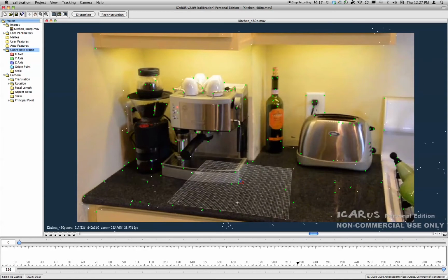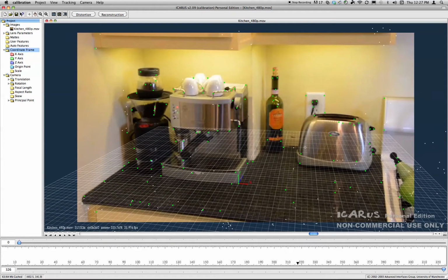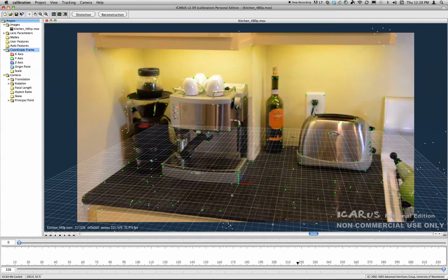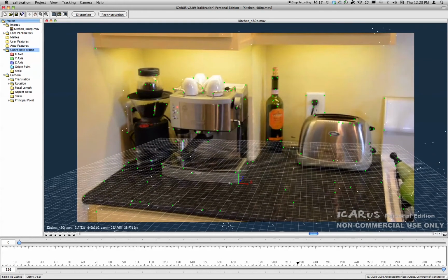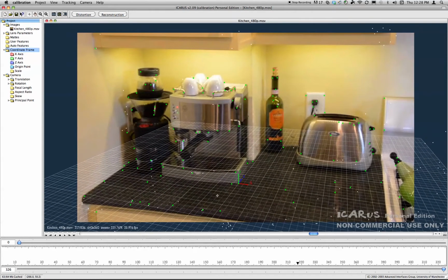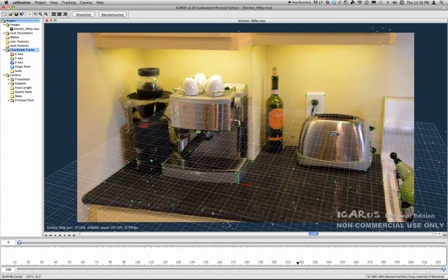And what we want to do is to enlarge this. So I'm going to keep rotating this around using Option and the buttons on the mouse. Middle button is going to scale it up. So I'm going to go ahead and scale this up so it's encompassing my view. And now I want to Command Option, left mouse button, rotate this plane in space, and angle it up and down until it's lining up almost exactly with the plane in my view.